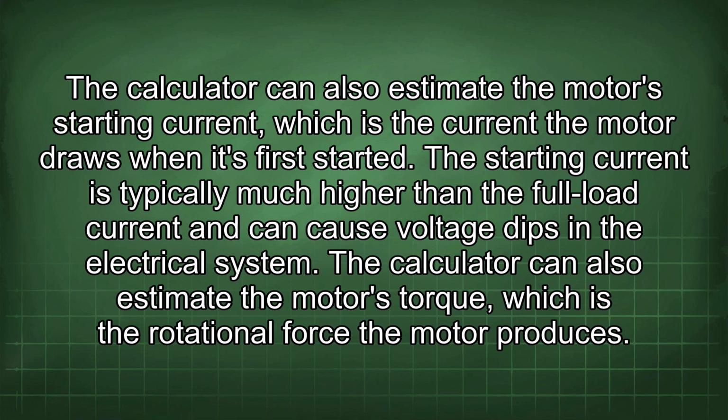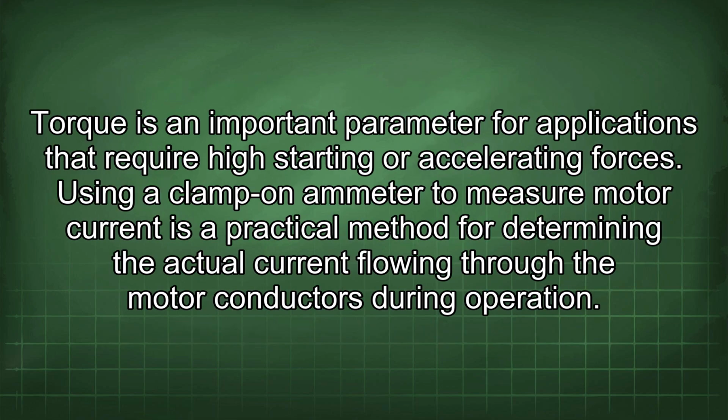it's first started. The starting current is typically much higher than the full load current and can cause voltage dips in the electrical system. The calculator can also estimate the motor's torque, which is the rotational force the motor produces. Torque is an important parameter for applications that require high starting or accelerating forces.